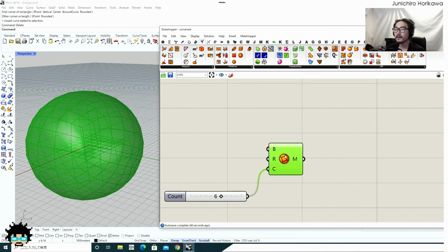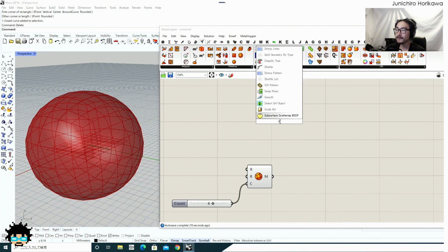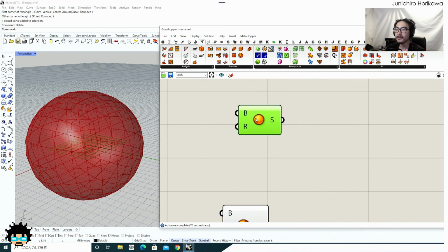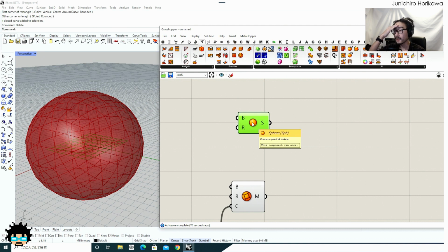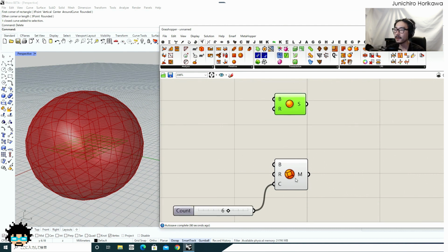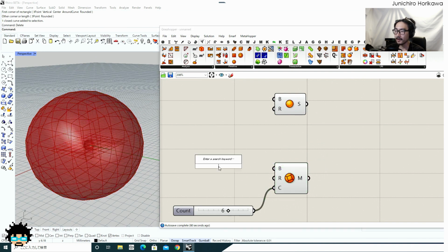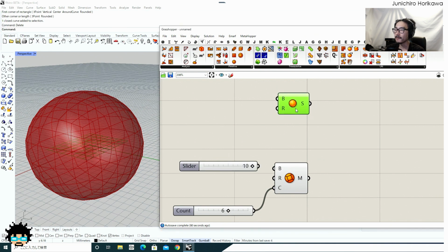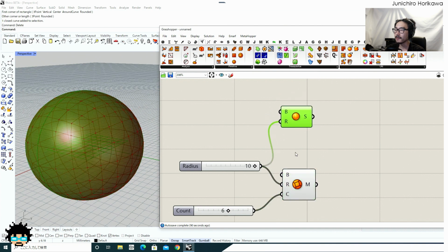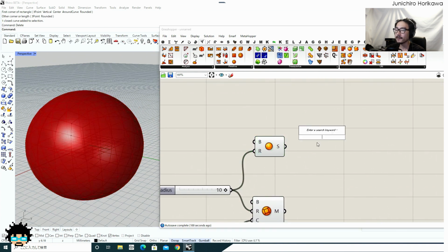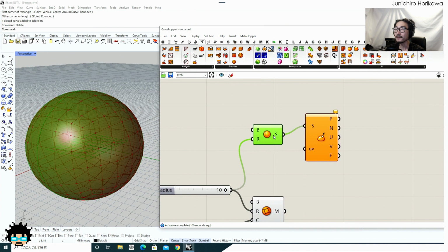And then let's also create an equivalent sphere surface, which I'm going to use in order to get the point position using a UV, because this is a mesh, you cannot define a position by UV. So I'm going to create two spheres of the same size, one with the mesh, one with the sphere. And for the sphere surface, I am going to use evaluate surface in order to pick up one of the points using this UV value.